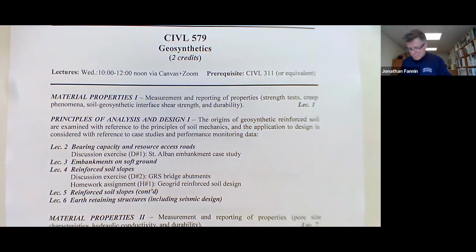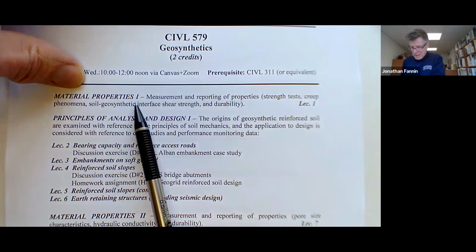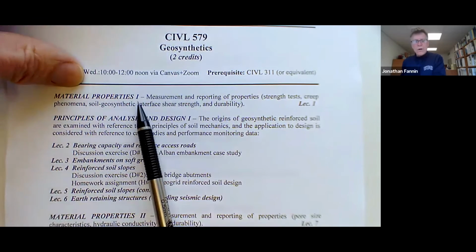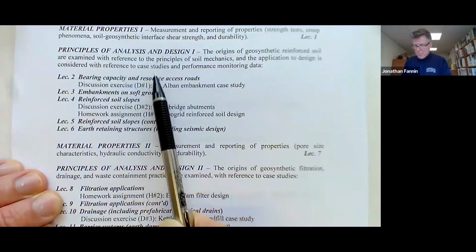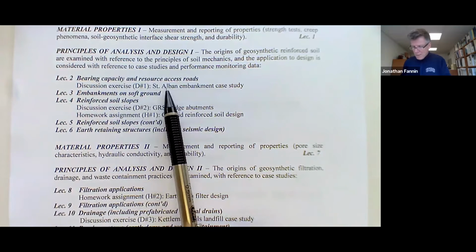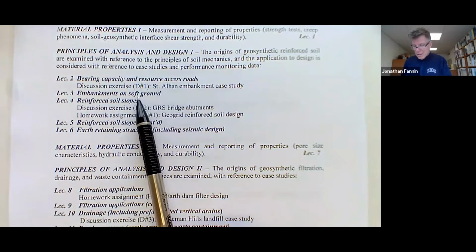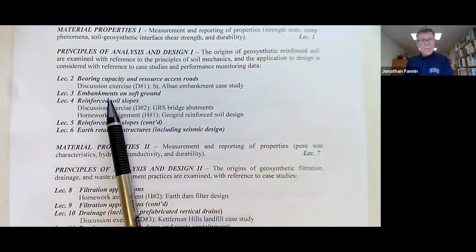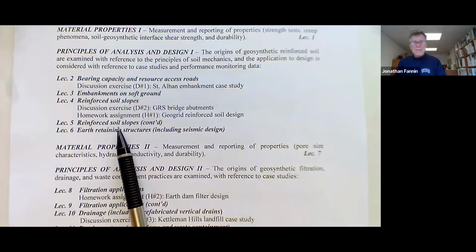So in the big picture, we dealt with material properties primarily related to mechanics and strength for analysis and design and support of reinforced soil structures, deformation tolerant through to deformation relatively intolerant reinforced soil structures. The live loads on relatively thin embankments, then more of a dead load or self-weight dominated embankments on soft ground, the sloped structures on competent ground, and then retaining walls on competent ground.